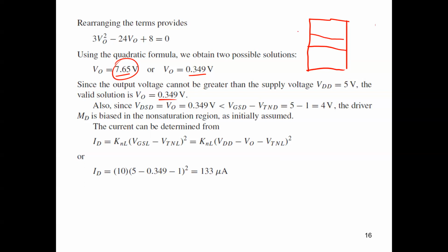So an active high signal, for instance, may start from 2 volt to 5.5 for some ICs, and active low may range from minus 0.5 volt up to, for instance, 1 volt. The area between is called the forbidden region. This is for some ICs, and it can differ from IC to IC according to the circuit design.